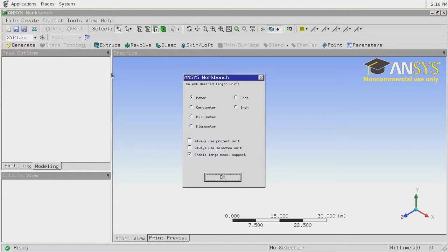So in order just to save time, I recommend you to go for RANS method if your tutor or your doctor accept it. And in order to do that, you will have to choose one of the models offered by the RANS method, and one of them is called K epsilon, which is a good one.